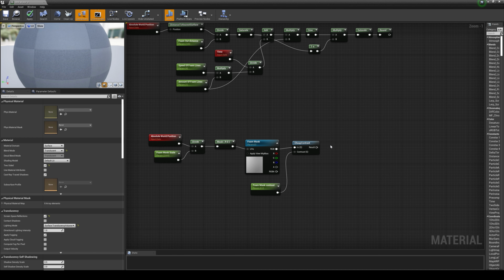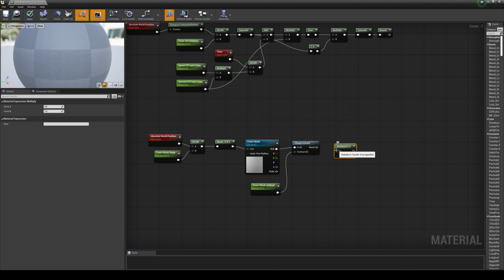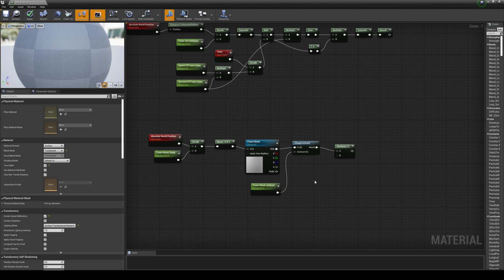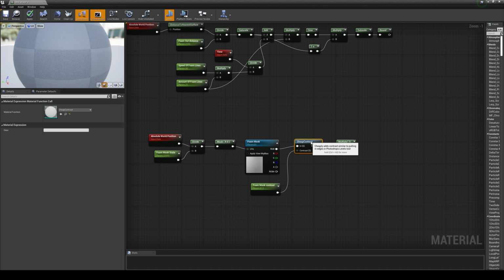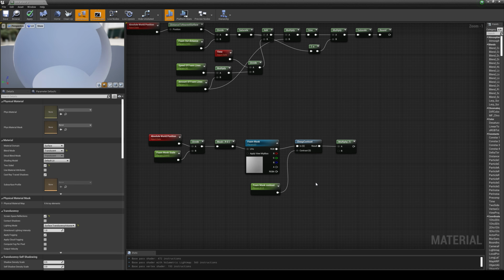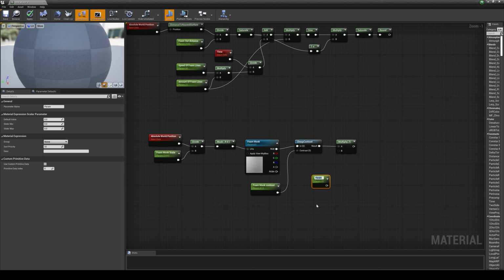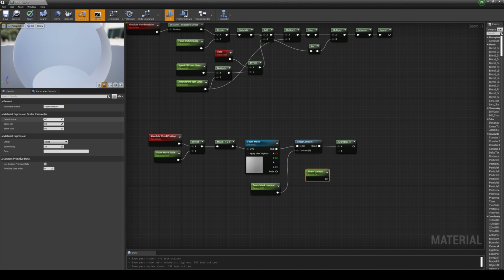Now we need to create a multiply node, M, and click on empty space, plug into A and create one more parameter node. Now we will regulate the form contrast, because it's the contrast of the mask and now of the form. S and empty space, and rename it to form contrast. And the default value we will change to 0.5.